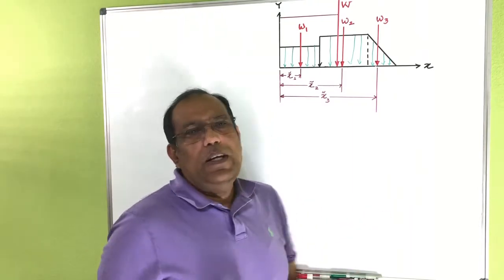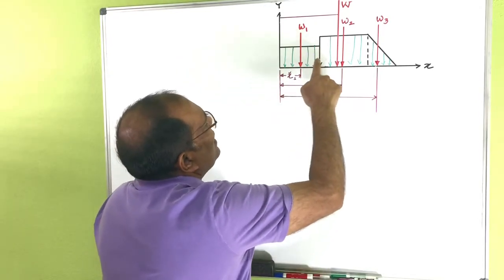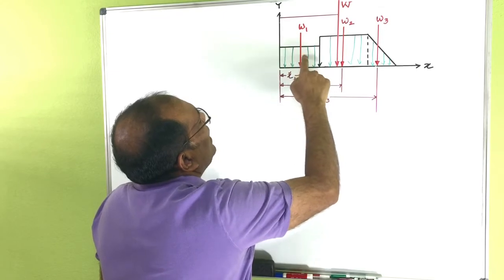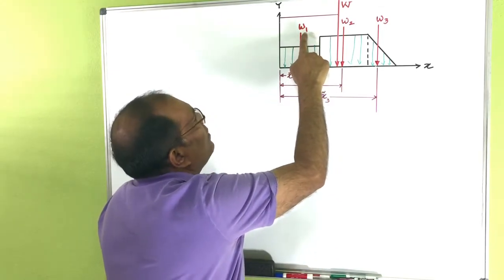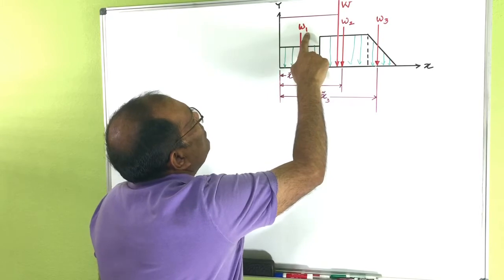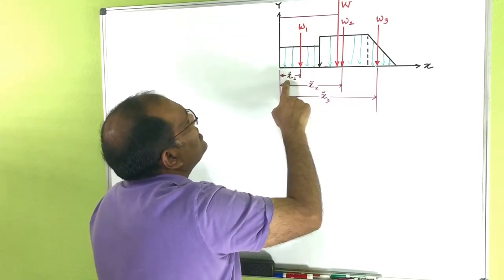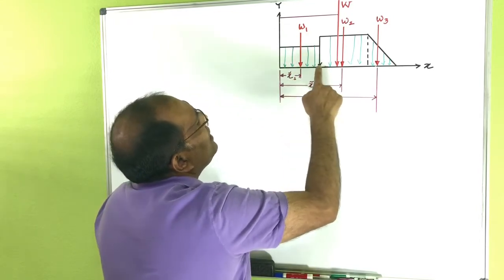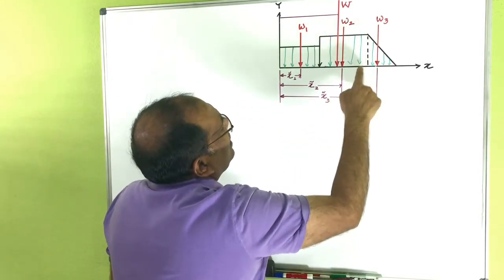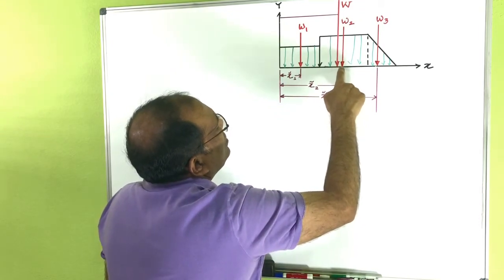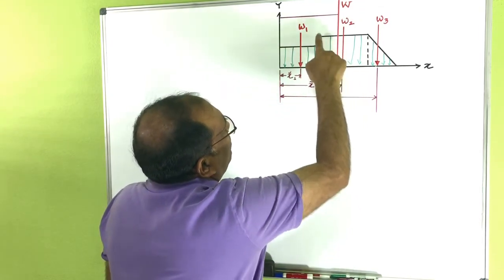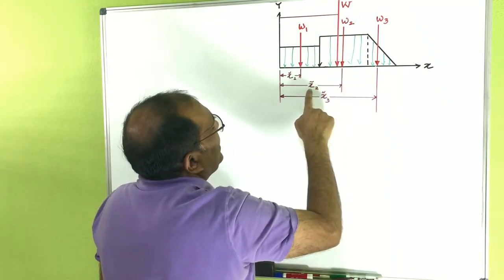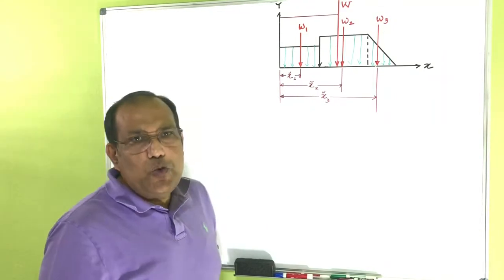For example, you can see here this is a kind of composite loading. For that loading I'm assuming this is the weight W1, and this W1 is working at a distance at the centroid of this area, which is x squiggly 1. Now I have another rectangle here, and the resultant force of this one is W2, working at a distance x squiggly 2.